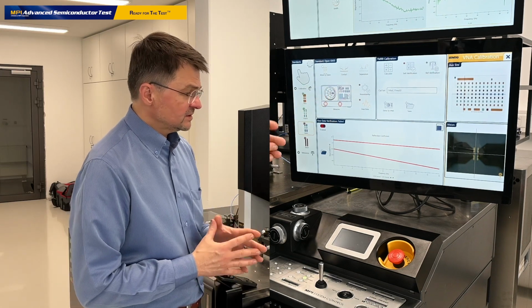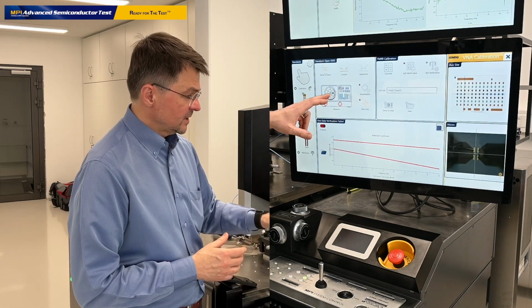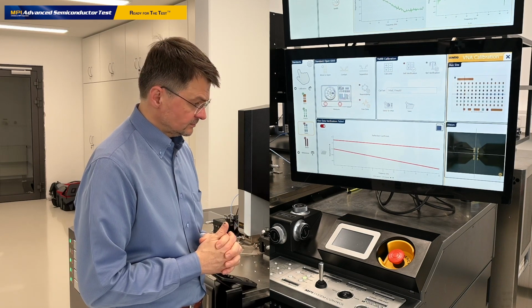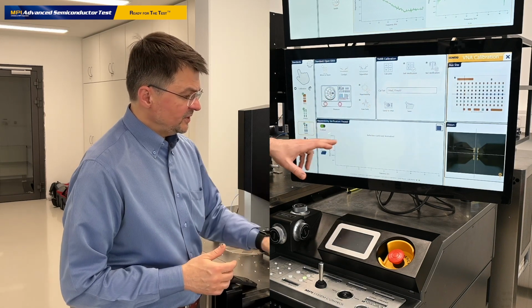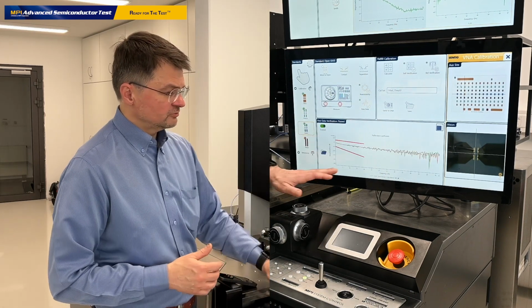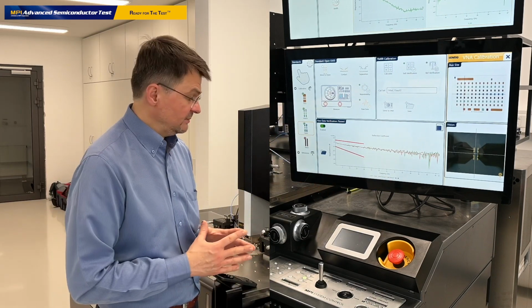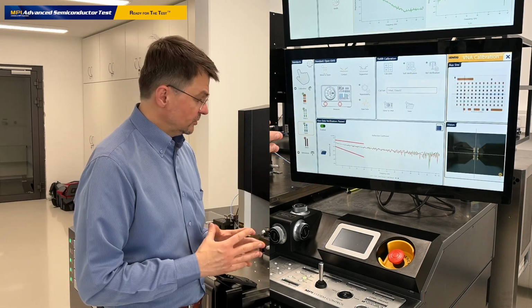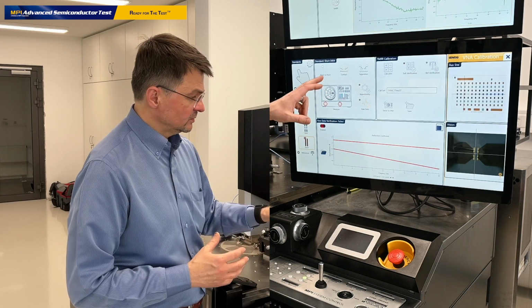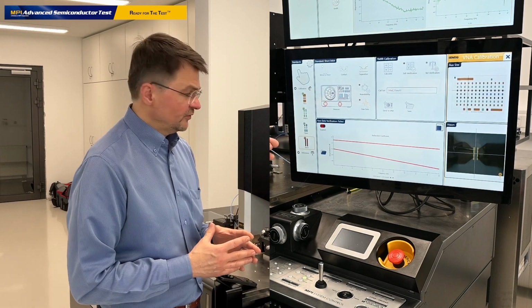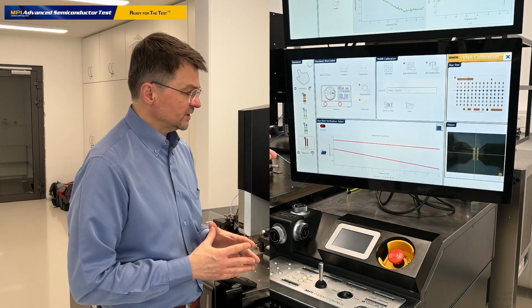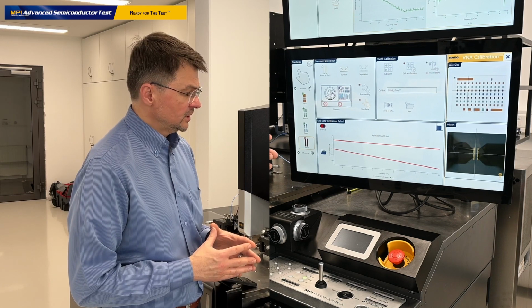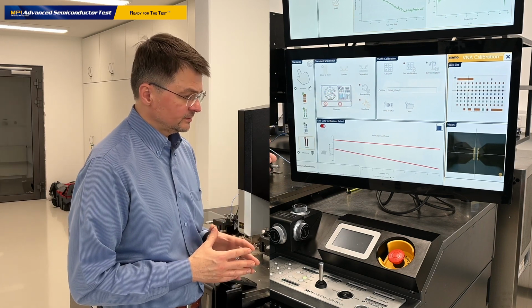Then go to the contact, measure. So repeatability of the measurement data is perfect. Raw data are within the defined boundaries. So it's all great. The last standard we want to do is the short standard. Move to the short standard, go to contact, and measure.